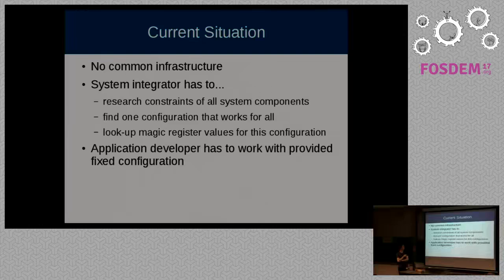There's no common infrastructure, and typically the system integrator, the person who puts together the converters onto this PCB and maybe writes some software, needs to research all the constraints of all the different system components. Different converters and different logic devices have different constraints for these parameters that I showed before. So you have to go into these data sheets and figure out how all of this works, and find a configuration that works for all of them.